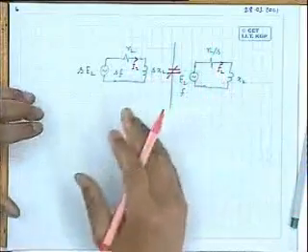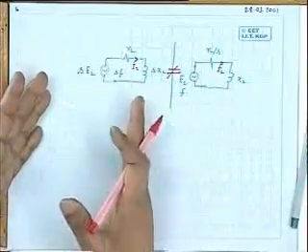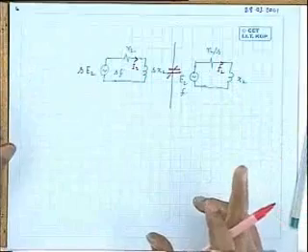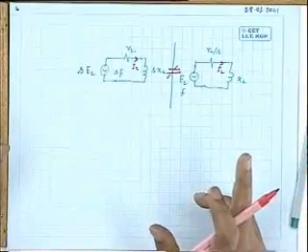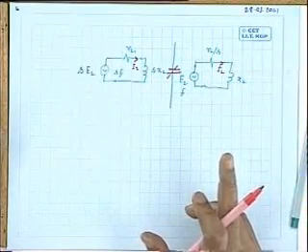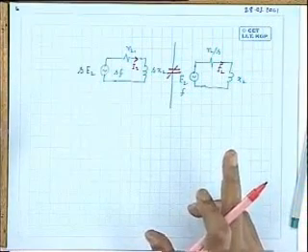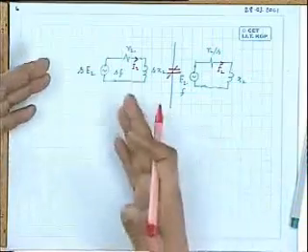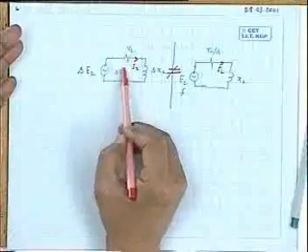The magnitudes of the currents are the same. I cannot say these two circuits are equivalent, as if two static circuits were drawn in one-to-one correspondence; not like that. Frequency is one problem, and another problem? The magnitude of the current is the same, but power is not the same.